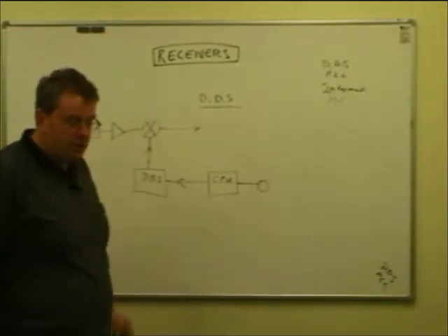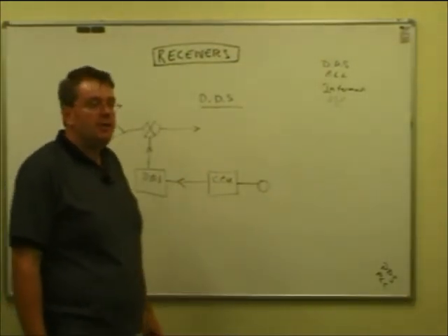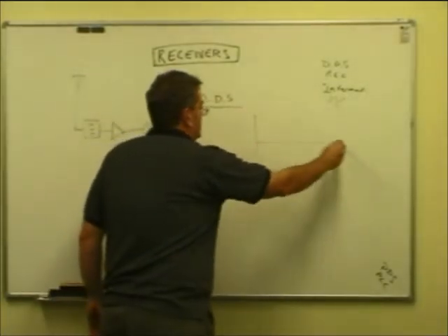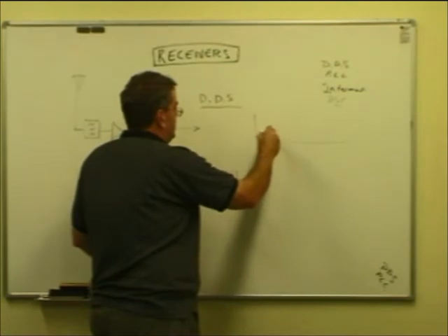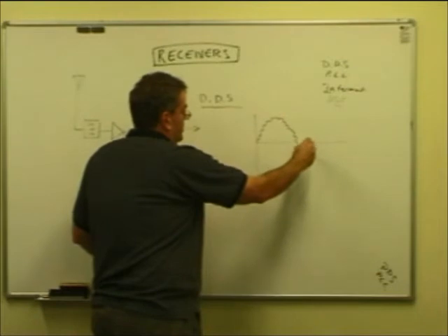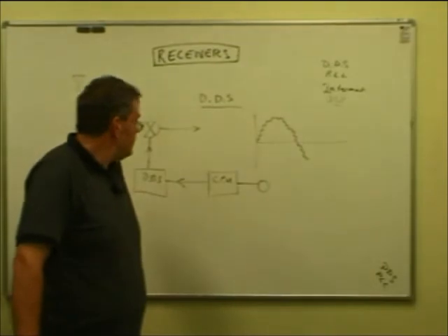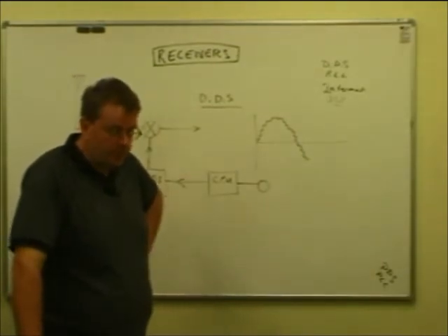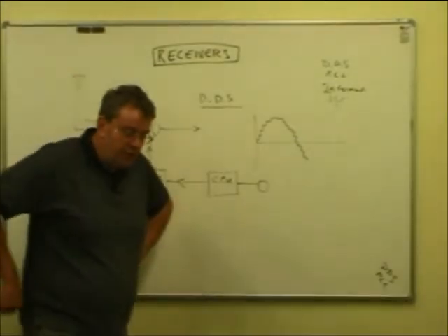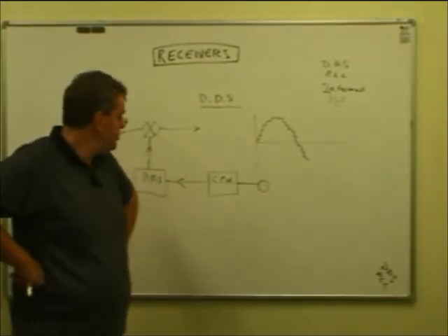And this is done using a digital system where the signal is actually manufactured, if you like. If you look at the local oscillator signal going in, it's a stepwise construction of a sine wave, which is then cleaned up by some filtering to make it look like a sine wave, but it's actually mathematically created. And that's the technology we're at the moment with modern radios, and it works very well. You don't have to have a sophisticated gearing arrangement and so on to a variable capacitor which can drift around.